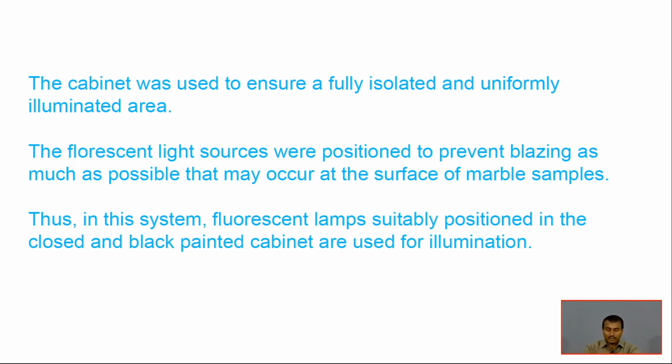Each and every marble is imaged only when the conveyor is stopped: image taken, it moves again, conveyor stopped, image taken, and so on. The fluorescent bulb is positioned so that there is no blazing, and we also position the bulb's angle so that there is no shade effect. We have also painted the wall of the cabinet black, so that there is no scattering of the light from the wall.